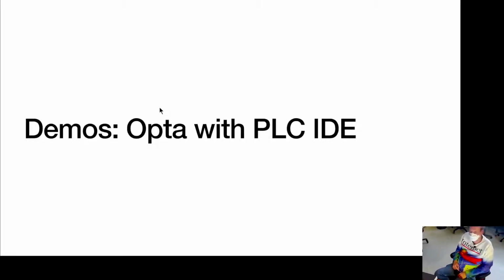As sort of a follow-up to that, could you still do the digital PWM output, but just use the relay as effectively just a contactor or switch? So send the PWM. What I'm saying is the physical relay doesn't actuate fast enough. Right, the operate and release time of the relay is not compatible with the frequency of the PWM signal, but can you still just use it to connect the line in or whatever you want to run your motor, and then also kind of power it with the logic controller?